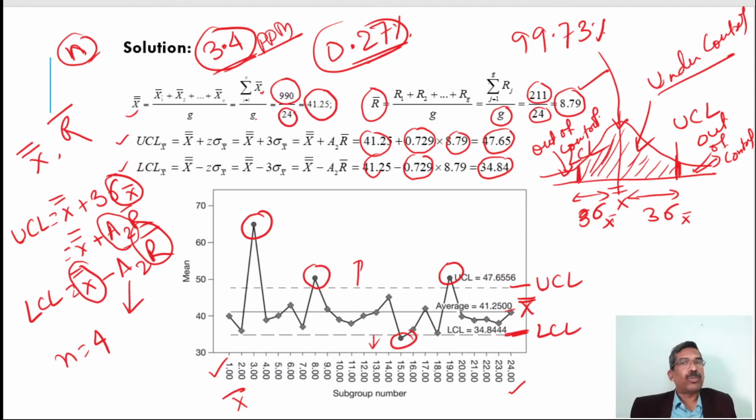If these four data are out of control, then it is required to revise the control chart once; again and again revision is not required. The first time you will have to revise this control chart, and this will be final. And then how to do the revision we will discuss later. At first we must discuss the R chart, because this is the X bar R chart. The R chart is also necessary here.